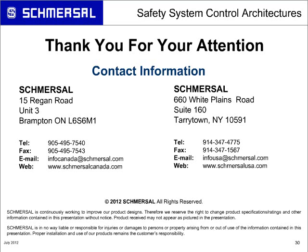Do e-stop buttons have to have maintain contacts, or can momentary contacts be acceptable, depending on the circuit design? When you look at the overall design of the e-stop, when you see older machines, you'll see e-stops that are momentary push buttons. I don't want to say momentary contacts, because normally the contacts that are mounted to an emergency stop operator head are spring-loaded type of contact. It's the construction of the e-stop operator head in conjunction with those contacts that makes the safety device.